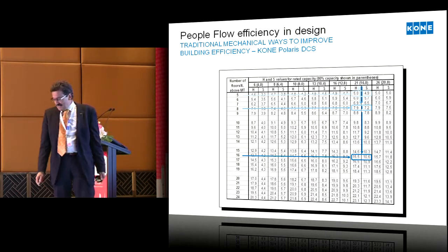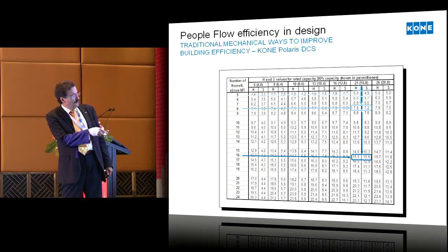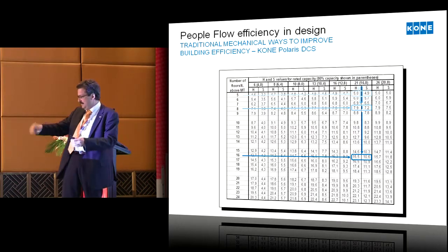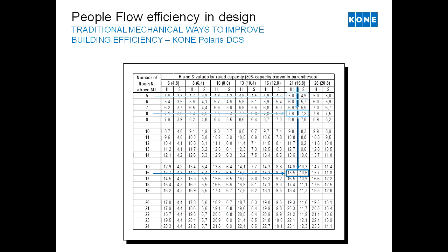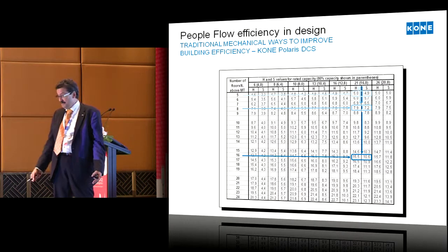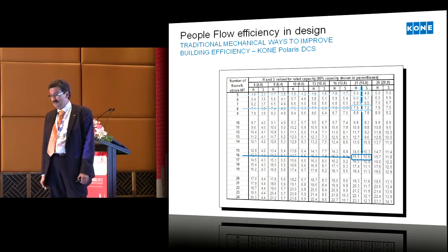So earlier, in the old system, I had 16 floors. I had 6 elevators there, which you could see. The minimum number of stops is approximately the number of stops divided by the number of elevators. So my elevator could be reduced to about 2.5 stops. Now my table only goes to 5, but at 5 I see I make 4.9 stops, so nearly 5. So at 2.5 it's going to be close to 2.5. From 10.6 to 2.5, that's 8 stops reduction. At 6 meters per second, that's 100 seconds faster round trip.